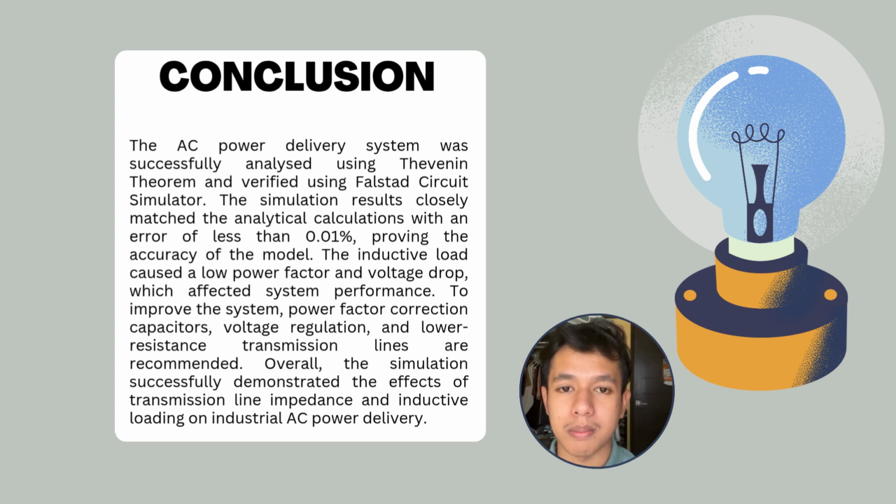them. Next, to prepare for our simulation phase, we calculated the exact physical inductance value needed at our 50 Hz operating frequency. This conversion yields 9.55 mH for line 1, 12.73 mH for line 2, and 55.49 mH for our inductive load. This mathematical groundwork sets up the parameters required to simplify the network using Thevenin's Theorem.